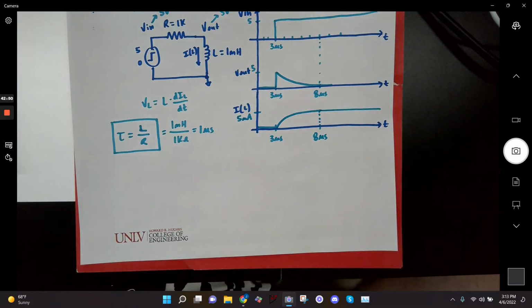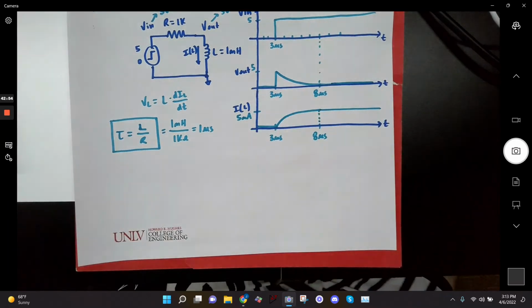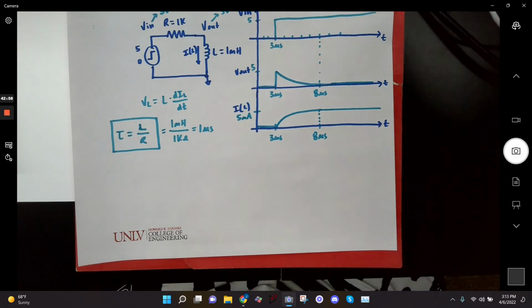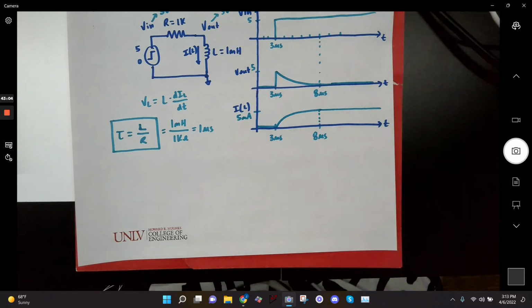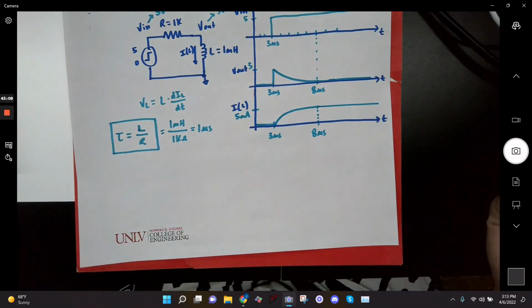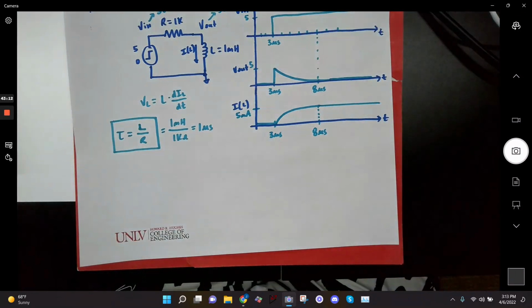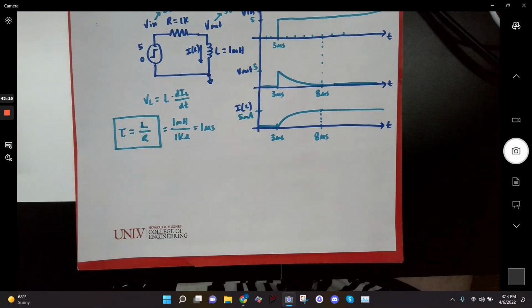Okay. I'm sure that there's questions. Does anybody have any questions about this? Yes. Just to clarify again, that means that there's no voltage difference on either side of the inductor, but it still has a current running through it. Exactly. So when there was 5 volts across it, there was no current flowing through it. And when there's no voltage across it, there is a current flowing through it. That might not always be the case, but that's very counterintuitive based on what we've learned so far.